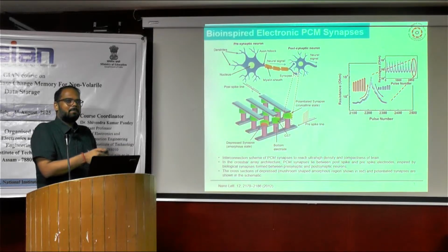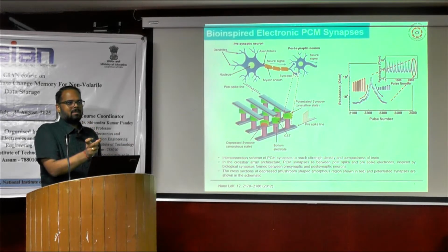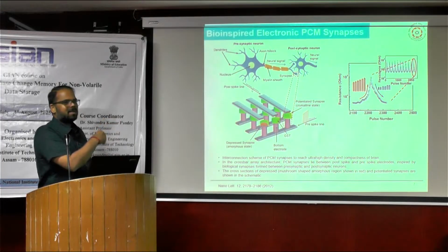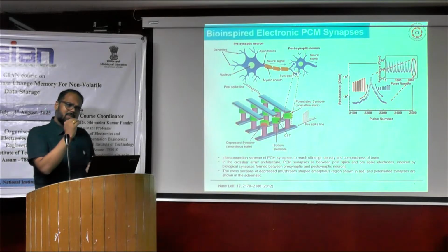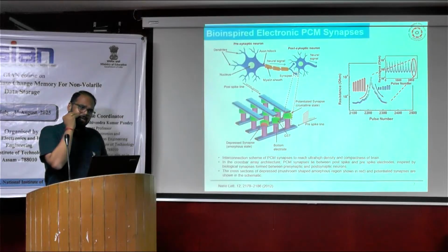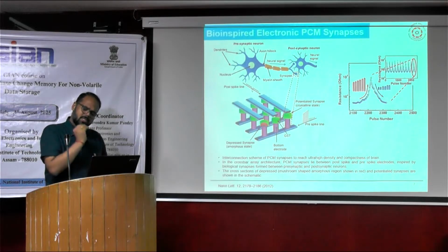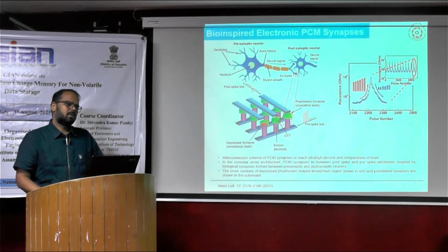So the depress pulse is relatively lower in width, so that you can get an amorphous region inside. If you are able to properly understand the principle of phase change memory, proper programming techniques, and set reset operation, then systematically you can tune your state for neuromorphic application. This is one level ahead. We can discuss more if you have questions.